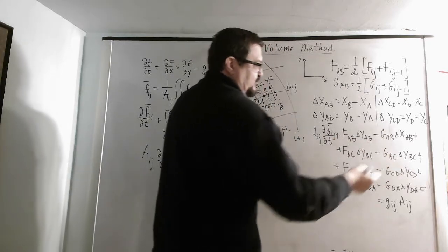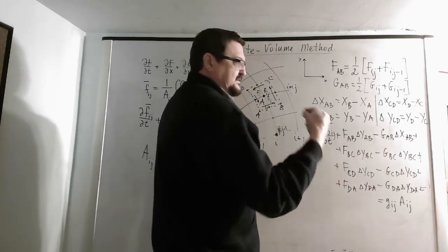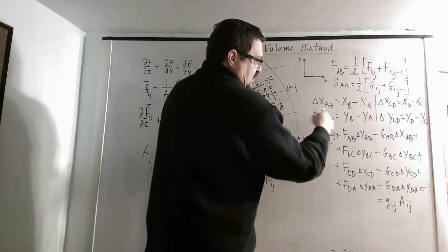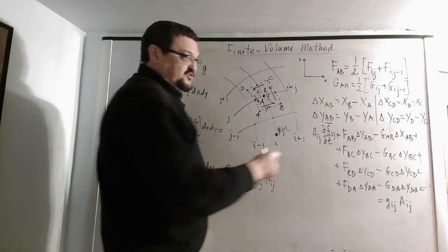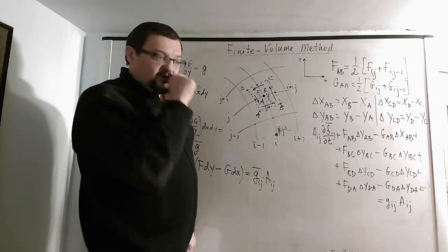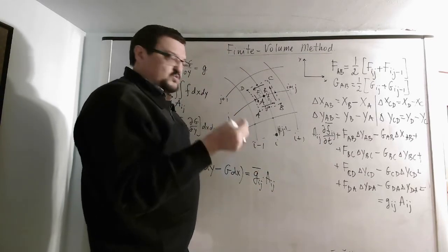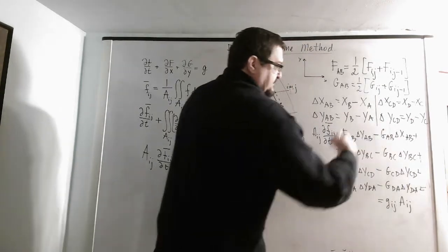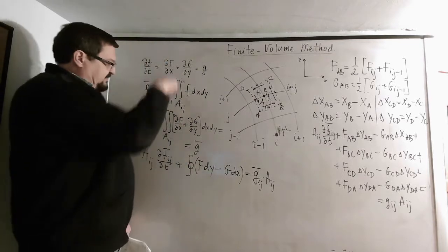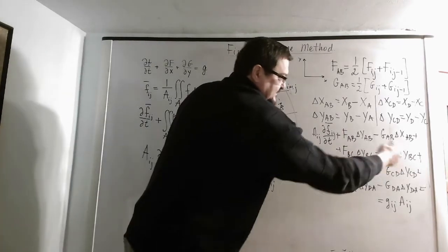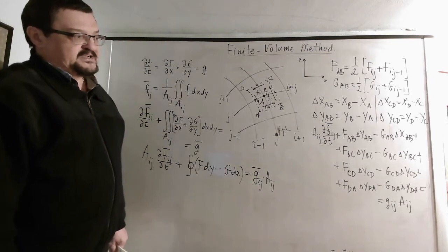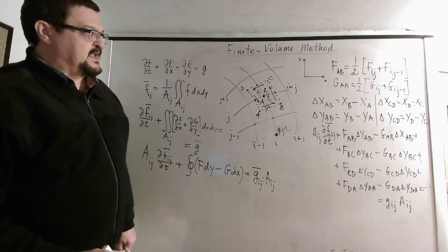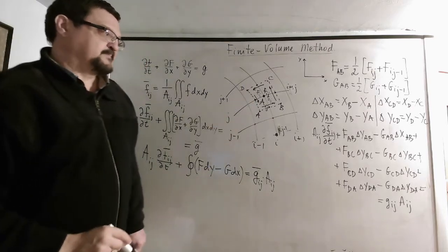Then this right hand side will be evaluated at time steps n, n minus 1 and n minus 2 if it's third order Adams-Bashforth, and so on. I don't specify this particular time derivative in this case. It all depends on you, which time derivative you use. But all your terms in space, we approximate like this, very simple algebraic equations. So just basically the summation of all these fluxes. And the fluxes can be easily computed.